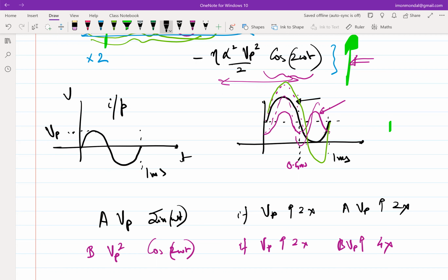If we apply a low pass filter at the output, then one of those things, right? His point is, if I apply a low pass filter whose cutoff frequency is between omega and 2 omega, then I can get rid of 2 omega, right? That in fact is one of the uses of a low pass filter. In signal processing, that is one of the uses, to get rid of undesired harmonics, right?